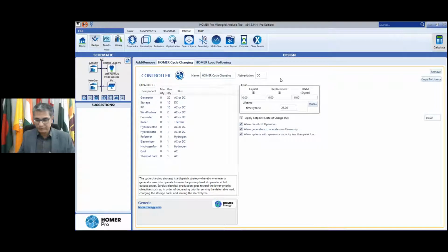If you want to model an off-grid system, you have to have a grid forming battery. If you want to model a system that runs without a diesel generator or a grid, you have to have a grid forming inverter. Absolutely. They're a little more expensive, but yes, you have to have a grid forming inverter. Otherwise you can never turn the generator off, or run with the grid down. Yes.